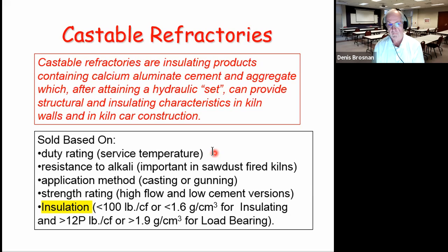So I took the bet and I lost the bet because that plant supervisor took a sugar sweetened beverage, a soda, and poured it in the form where I was packing the form with castable, and it never set. Came back the next morning and I had to pay up because it never set. So sugar is one of the ways that you can delay setting of castables. Other organic liquids can do that.